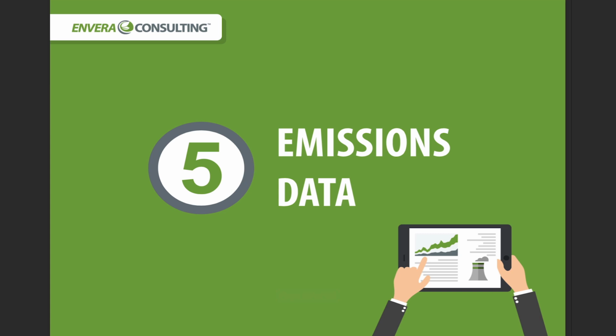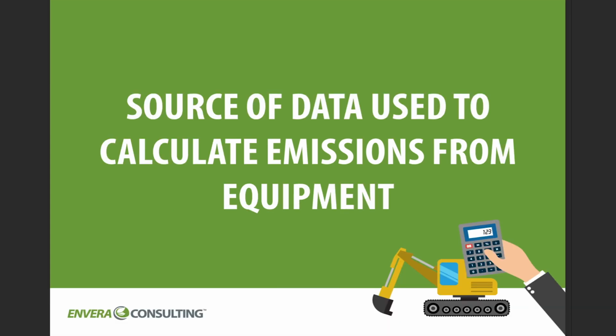Number 5, you want to talk about emissions data. In this case, you want to talk about the sources of data that you'll use to calculate emissions from your piece of equipment. Emissions data, or the data used to calculate emissions, can come from a variety of sources. It can be lookup tables such as AP-42. You can use agency documents. It could be SDS or MSDS sheets, manufacturer's data. You could use engineering calculations. You can use an emissions guarantee. It could be a source test, direct measurement. Whatever the case, you want to provide the sources as well as the data that you'll use to calculate emissions for this specific piece of equipment.